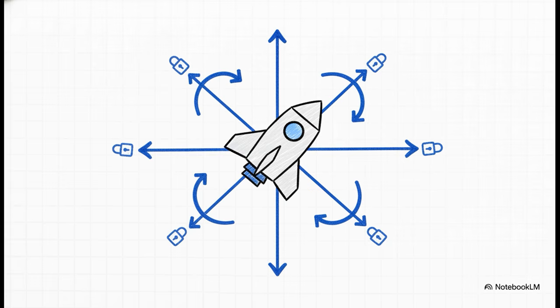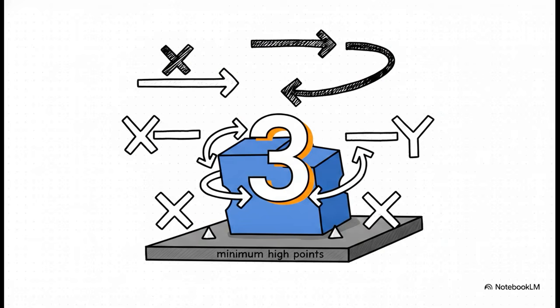And it can also rotate or tilt around the x-axis, around the y-axis, and around the z-axis. Picture a spaceship floating totally untethered in outer space. To inspect a part accurately, we have to lock down all 6 of these movements relative to our measurement equipment. So, jumping back to our quiz.